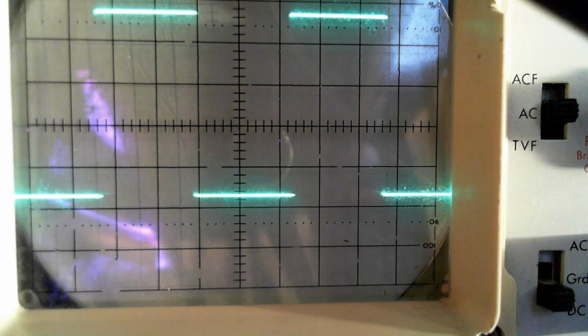You know, it could be because of the low impedance input to the scope. Now, I really do need to use a scope probe, but the scope probe has to be compensated properly. Maybe we'll go back to the previous step. I'm not using a scope probe right now. I'm using a 50 ohm test lead with BNC on both ends. Maybe I'll put the probe on, and then I have trouble picking up this signal.